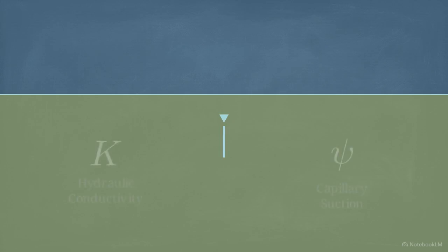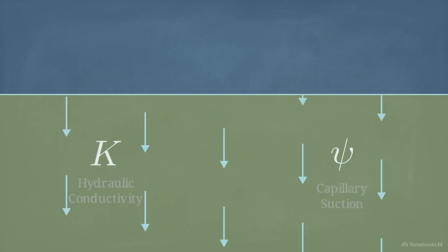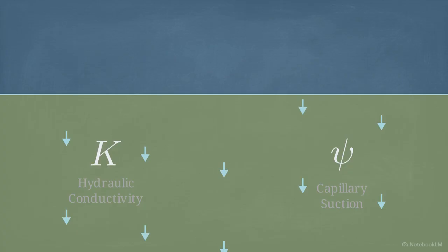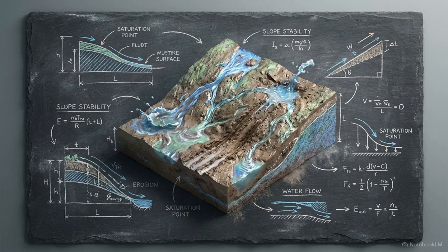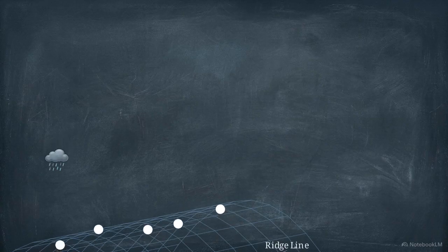To mathematically subtract this absorbed water, we use the Green-Ampt infiltration method. This physical model calculates the absorption rate based on the specific hydraulic conductivity and capillary suction of the local soil. The water that remains on the surface after these infiltration losses are calculated is defined as effective rainfall. This effective rainfall is then routed down the natural slopes of the catchment geometry using a unit hydrograph.